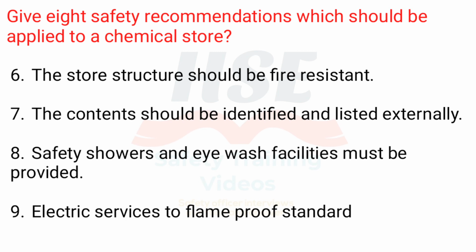6. The store structure should be fire-resistant. 7. The contents should be identified and listed externally. 8. Safety showers and eye wash facilities must be provided. 9. Electric services to flame-proof standard.